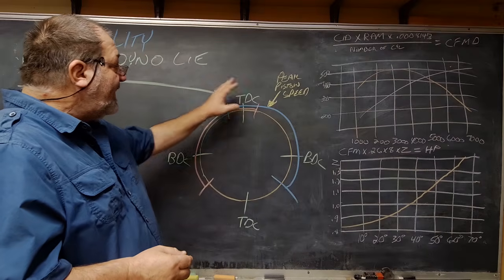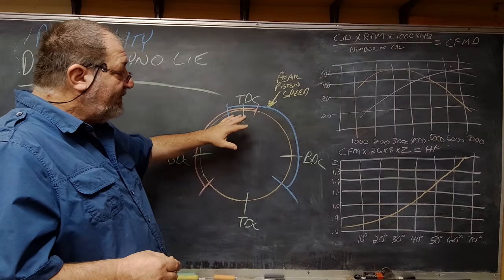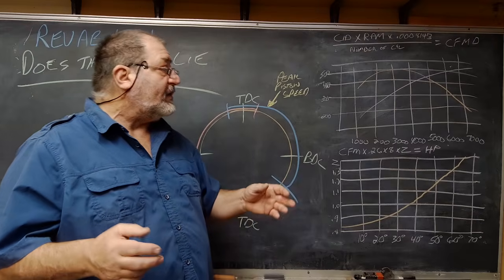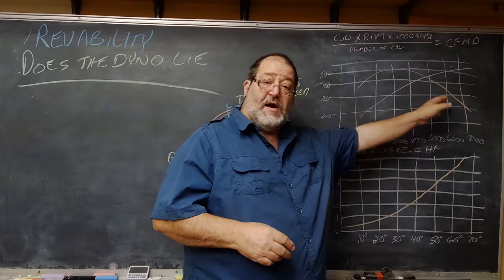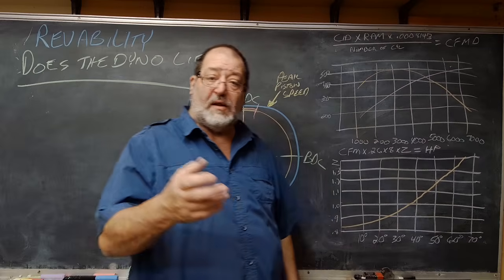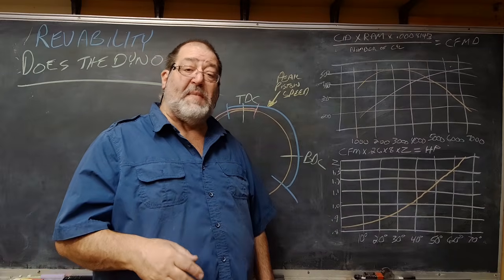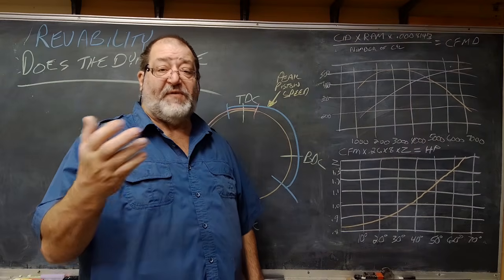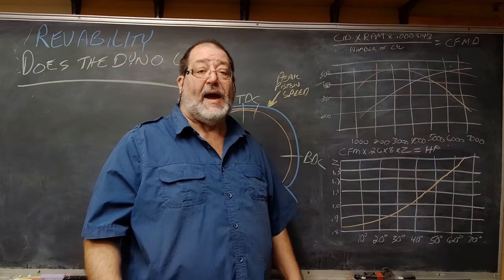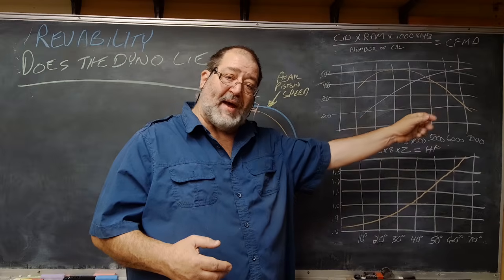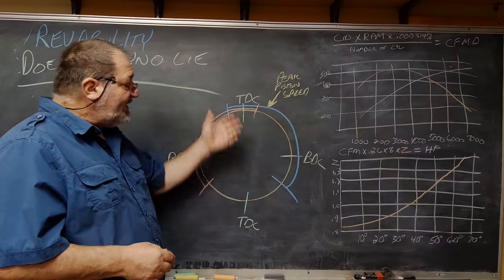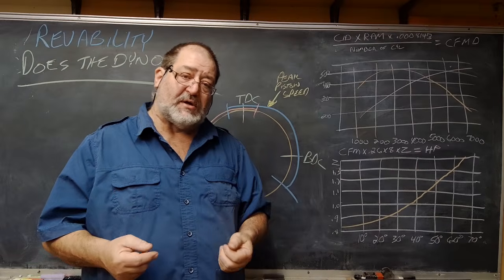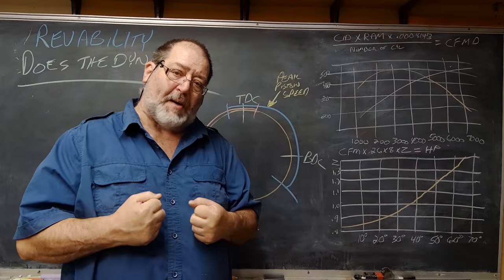And a lot of that has to do with the cam events having been fine-tuned, certainly in the RPM that they're working in. You know, one of those kinds of engines, you may be working 5,000 to 9,000, maybe even 5,500 to 9,500. And so you're way up there in the RPM band. But you need to address that issue well enough that the engine doesn't feel bottled up.